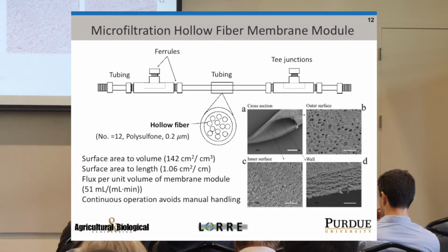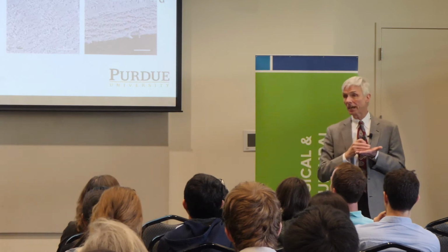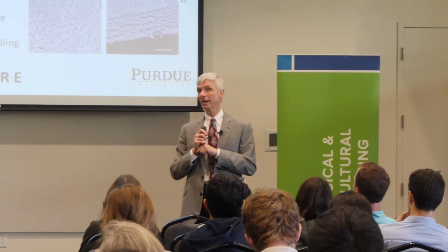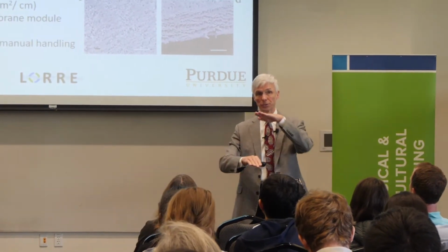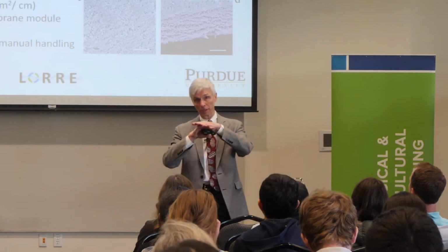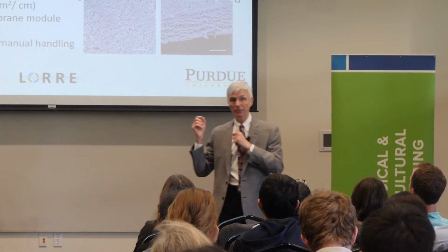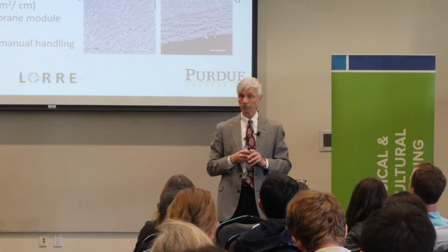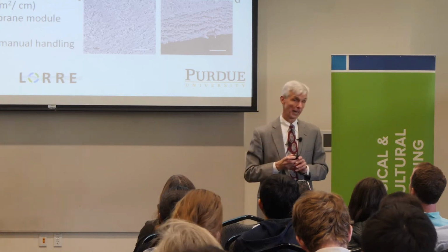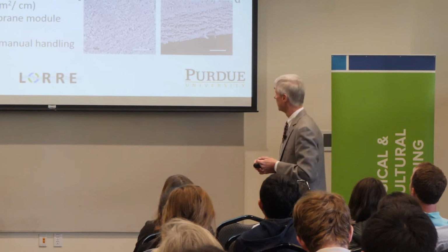And then on the inside surface, there would be a coating. The cutoff of the hollow fiber, which was between 0.2 and 0.45 microns or so, was due to depth. So if the cutoff is a lower molecular weight, the depth is higher, right? Because it's more tortuous. So these are not through pore, but rather depth filters, fabricated in a very small diameter, roughly the size of a hair, to give you a lot of surface area per unit volume.